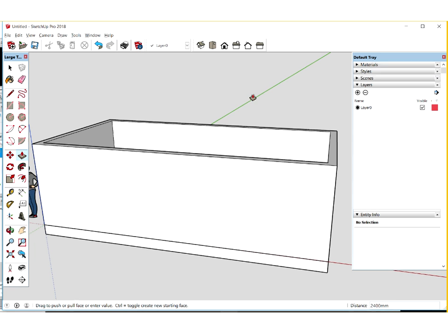Now this is my workflow whether I'm building a whole house or a multi-story building or just a single room. Okay, so for those of you who are doing a subject where you've got a project where you want to build a room or a bigger building, this is the workflow I would use. Now obviously if your floor plan steps in and out, you just take longer, you set that floor plan out first. I always start with building the floor of the object. I don't start with the walls, I start with the floor and then place, think about building a real building. Whether it's a timber flooring system or a concrete slab or whatever it is, I'll build the floor first, then put the walls on top. So it's sort of a logical order to working.